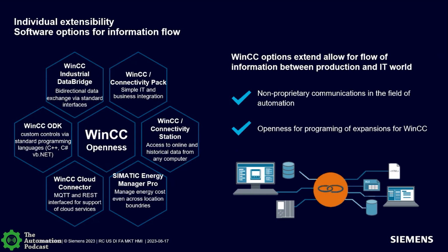And another little package we have is SIMATIC Energy Manager Pro. That can be used just to help you monitor and maintain your energy usage. Now, when we talk energy, we're not just talking maybe electricity or water, but we're also talking anything that you flow through your plant. Is it gas? Is it electrical inputs? Is it air power? Stuff like that. As long as you've got a meter out there that's metering your usage, you can bring it back in Energy Manager Pro and start predicting it, and charting it, and seeing where it is.